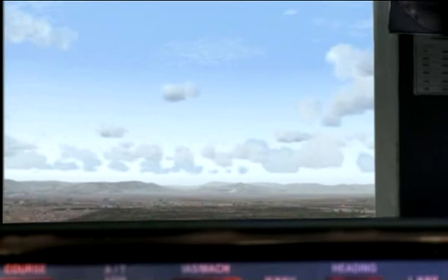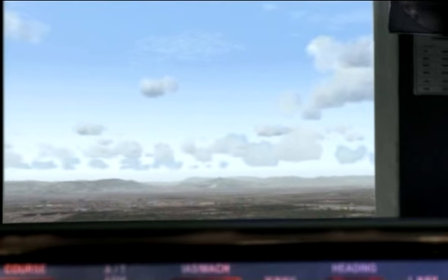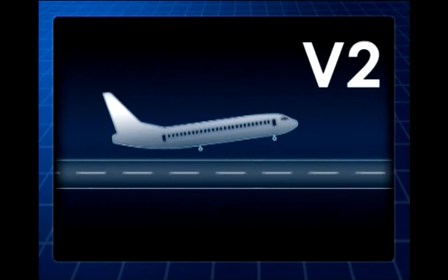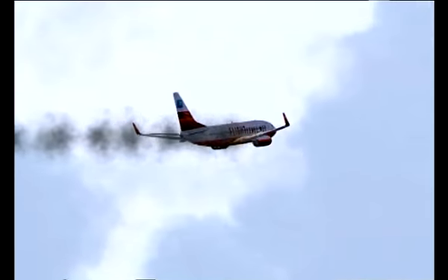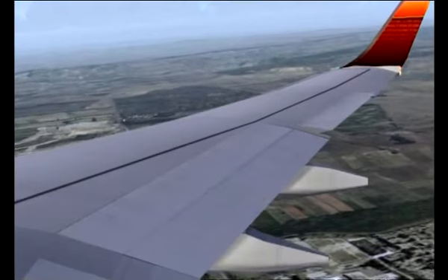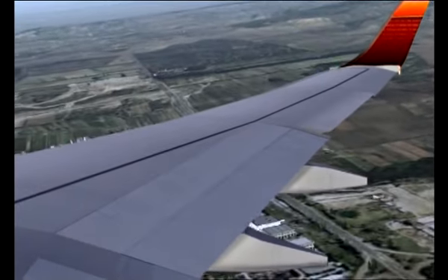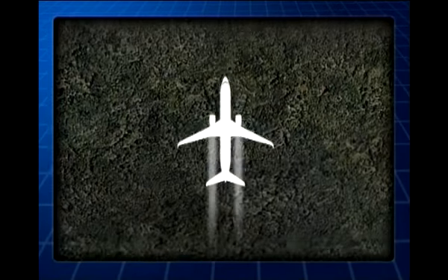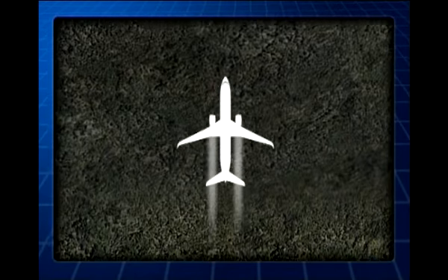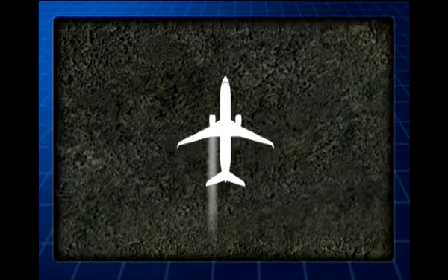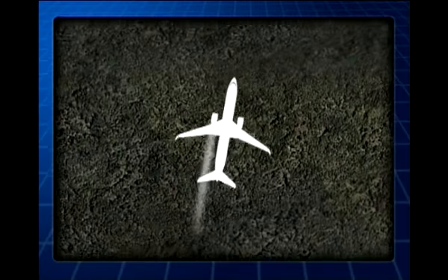400. Heading select. For safety, the entire takeoff procedure is designed to ensure that the aircraft will be able to climb at V2, the minimum speed should one engine fail. But flying this type of aircraft with only one engine operating is very hard because of what is called asymmetric thrust. The jet engines mounted under both wings normally produce equal thrust. If, however, the thrust of either engine decreases, or, in case of an engine failure, thrust becomes asymmetrical.